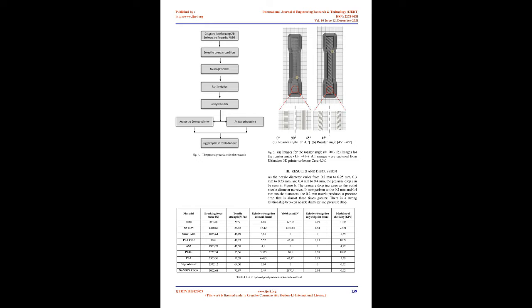13. The samples for the strength tests were prepared according to PN-EN ISO 527-2. Files were created in STL format and saved in Autodesk Inventor 2018. Figure 3 illustrates the sample shape with its characteristic dimensions. Figure 4 shows the model of each printed sample oriented along the x-axis. Table 2 summarizes the filament data used for the sample.